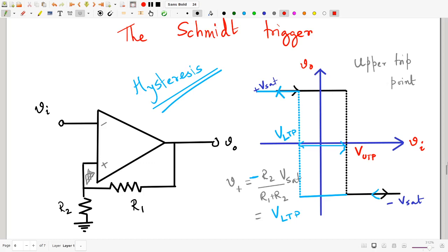On the other hand, if you use a Schmitt trigger, where the center of this hysteresis loop is at V reference, and the width is controlled carefully so that any noise will be within the hysteresis loop, just think about it. Then the output will switch only if you cross the threshold and go beyond it and cross over to the other side. That is, you have quite a lot of buffer within which the output will not switch despite your crossing the reference voltage.